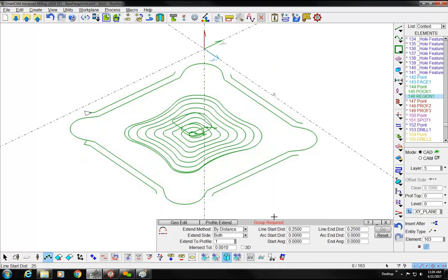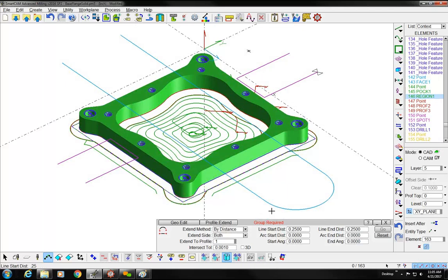And so what I got was all of these step 20 elements, the inside and the outside, using a combination of hide selected, hide unselected, and invert visibility. And I'll bring those all back. Okay, I want to move on to view filters.